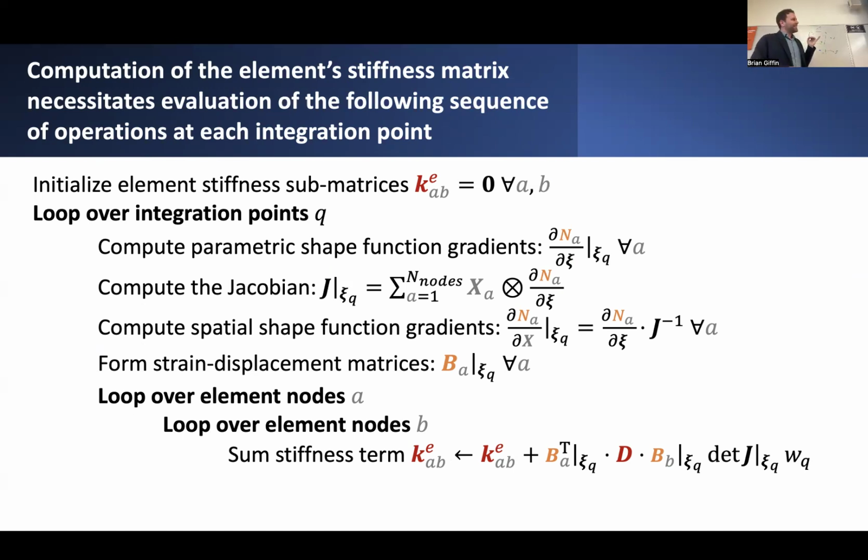The first is, it's useful to know that there are distinct discrete values inside of the element in order to interpret post-processed results. If you're looking at some finite element analysis, you run it on a computer using Abaqus or ANSYS or whatever preferred software you use. When you visualize the results, oftentimes they present it to you in a nice, colorful way. They usually have nice interpolated color plots. Sometimes they'll plot just a single value per element. Sometimes they'll interpolate and linearly smear out some of the results.